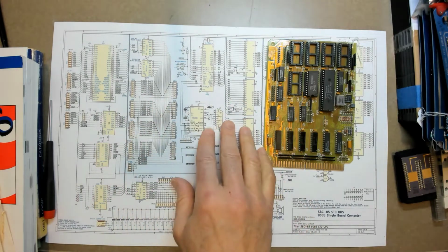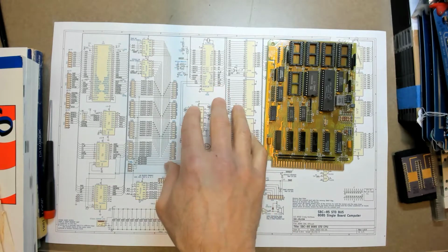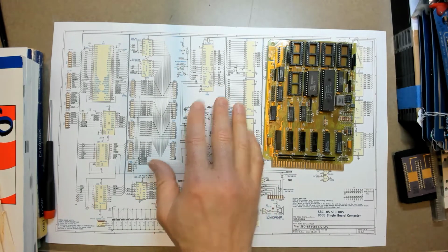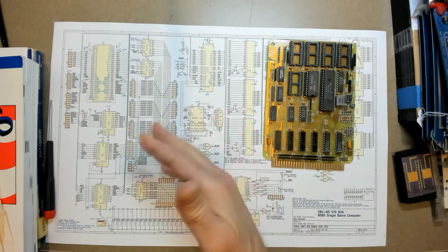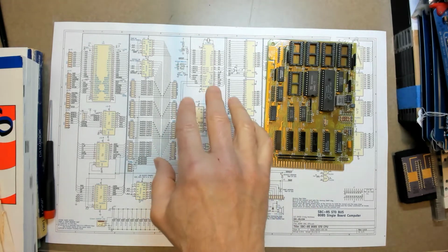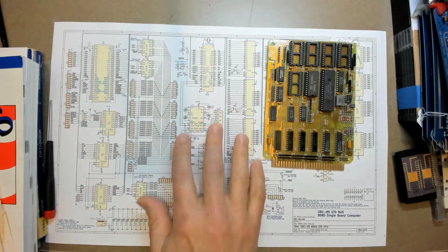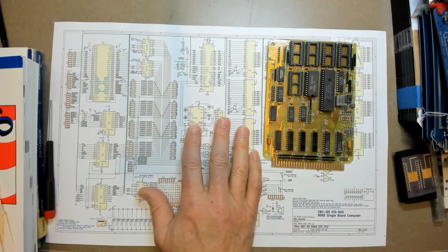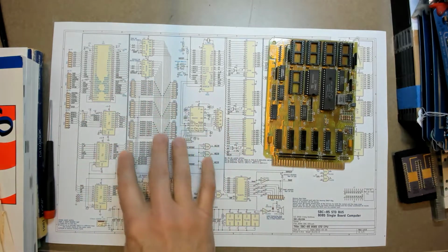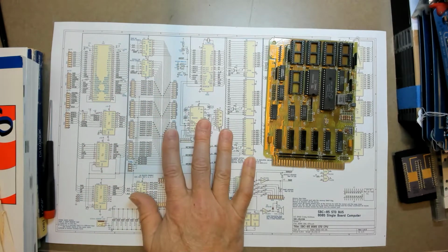Since DMA is quite literally hardwired to do memory transfers, it is of course faster than the processor could even consider running a block transfer program. So while it's not required to be compatible, DMA was a key aspect of any respectable STD processor card, and so I thought it was important to make sure that this card would be DMA compatible.